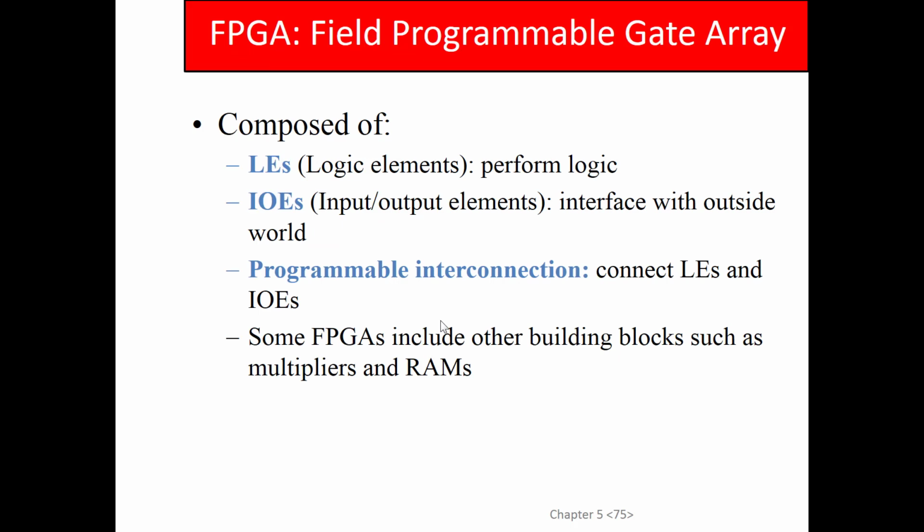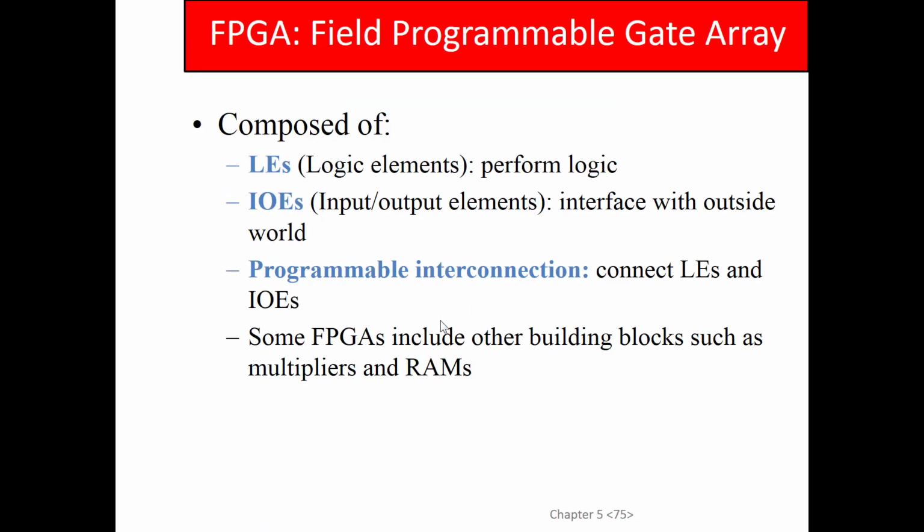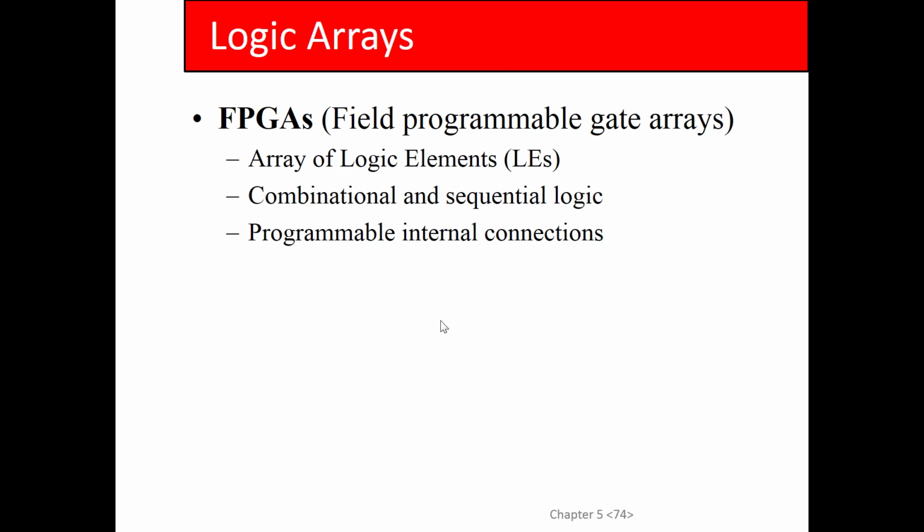Okay, and then the last thing I want to mention here is RAMs can be used for logic as well. In particular, there's these devices called FPGAs. Basically, if you want to design hardware, you just have 2 choices. You can design hardware and send it out to be fabricated, which takes time and costs a lot of money, in which case they would send you back a physical chip, an application-specific integrated circuit.